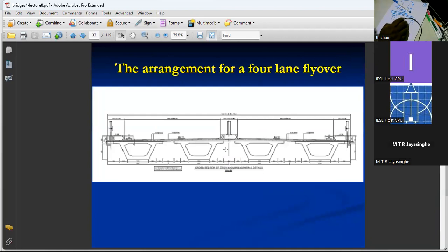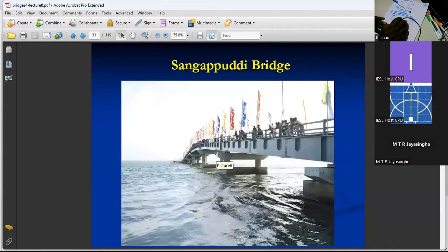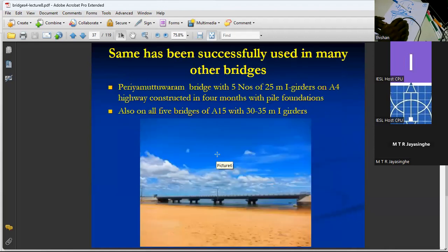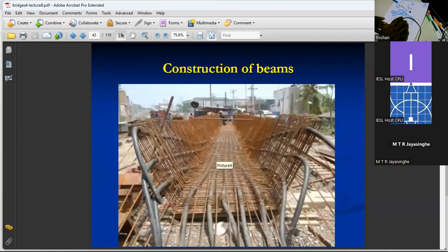These are the kind of beams that we used, and because the original design was box girders of about 1.35 meter depth, even with these beams, we had to match the original depth, because we had to ensure that the profile of the road, the highway profile, was maintained. So we use that, and so I can go further and show you the situation.